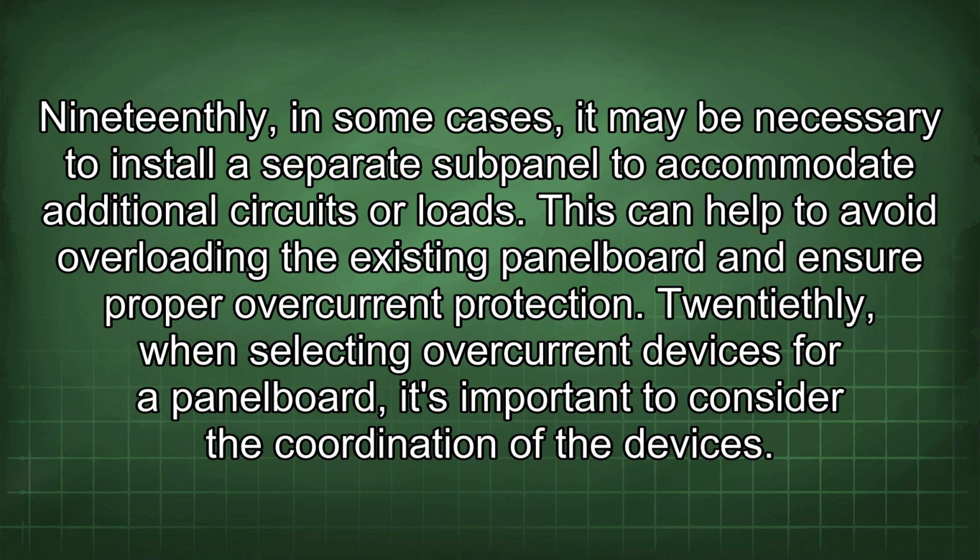19thly, in some cases, it may be necessary to install a separate subpanel to accommodate additional circuits or loads. This can help to avoid overloading the existing panel board and ensure proper overcurrent protection.